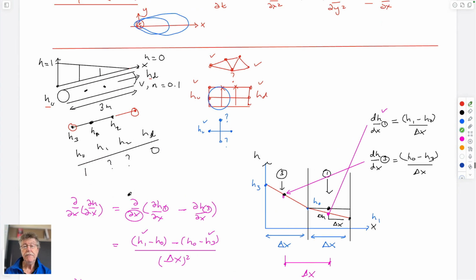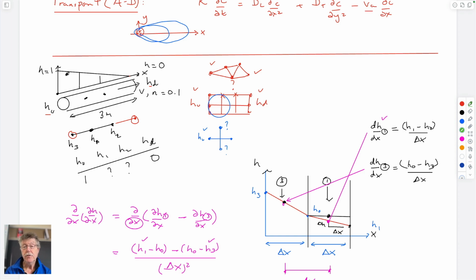And so if it's uniform permeability, you know from Darcy's law that V is equal to K over mu, no, sorry, hydraulic conductivity, hydraulic conductivity dH dx. You know that the velocity here is the same as the velocity here, which is the same as the velocity here. So this is constant. Permeability, hydraulic conductivity is constant, so that by inference the gradient has to be constant. So all these gradients have to be the same.